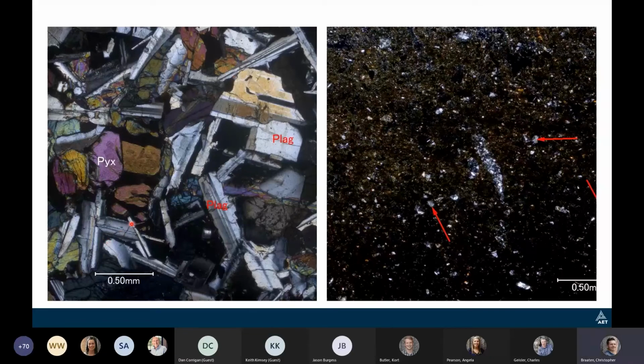So I wanted to show this as another example of why we might do C295s on quarries. This is actually a quarried basalt from Washington State, the West Coast, and got these thin sections, dug through the sample, started seeing all these nice angular crushed crystalline basalt particles, got them in thin section, beautiful thin section of the basalt, nice plagioclase crystals.